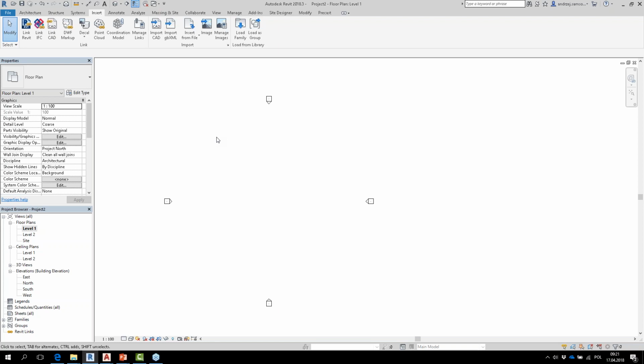This means that if I save my Revit model with an imported CAD, I can send it to someone or move it, and this 2D CAD will follow my file. Very comfortable, but remember, this also has some limits or disadvantages, because if I import my CAD, I cannot update it from the AutoCAD file or any CAD file anymore, because it's already here in Revit.